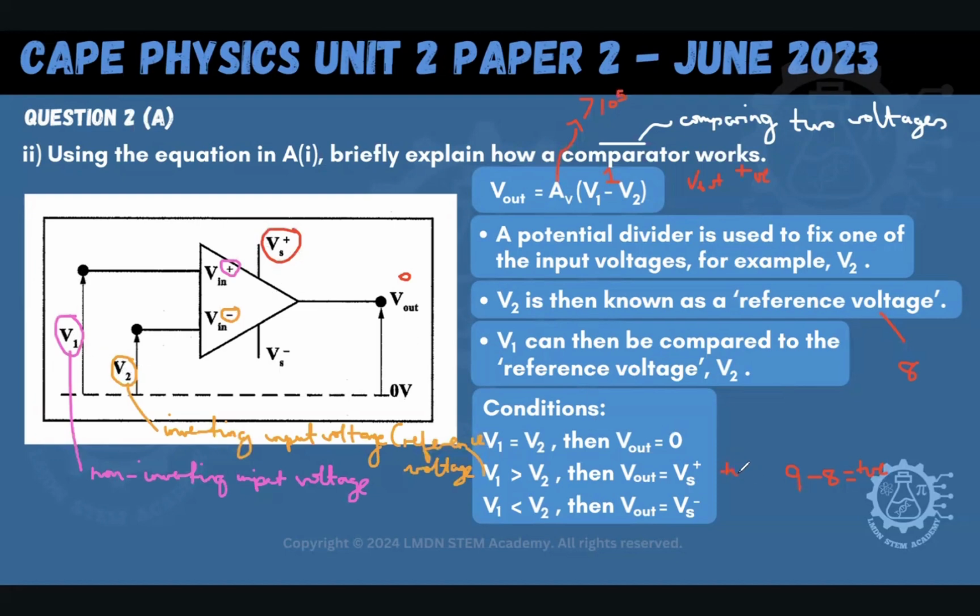Whatever V1 you put in is larger than your V2 because you see a positive saturation. We call that positive saturation, and that's when your V1 is larger than your V2. So that's the second case that could happen, and that's a comparison. That's one of the things that a comparator could tell us. All right, so let's look at the third case now. Let me just leave that there for now and take this one out.